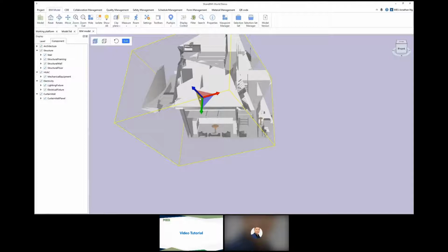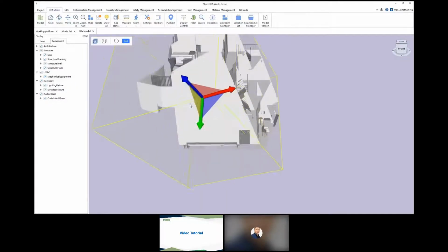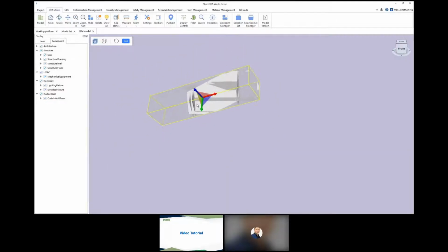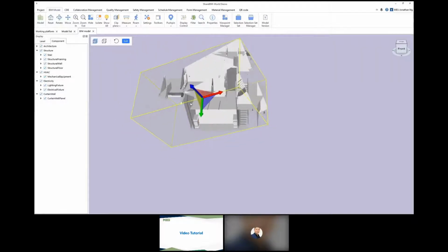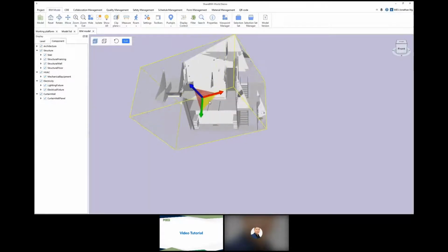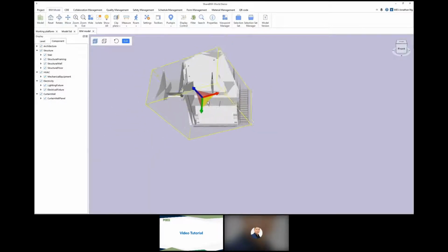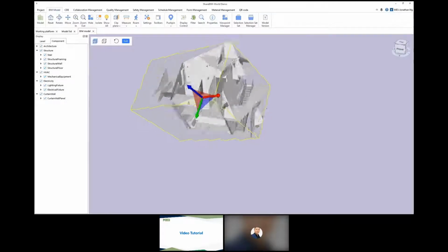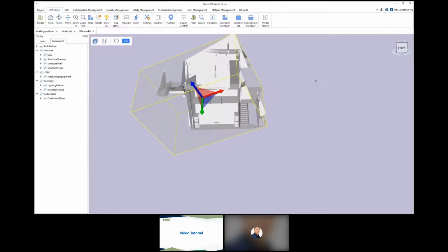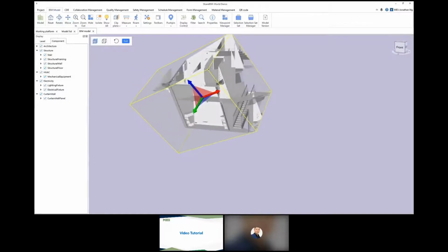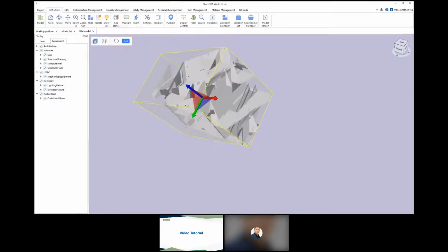So basically if I select this face, what it's gonna do is zoom in and out along the blue and green axis while holding the red axis constant. So I can, yep, have it focus on just this part. Okay, this is not very good, not nice doing that. And then I can do it holding the blue axis constant and zooming in and out of here as well. Yep, so that's how we can achieve multiple cross-sections about the model.